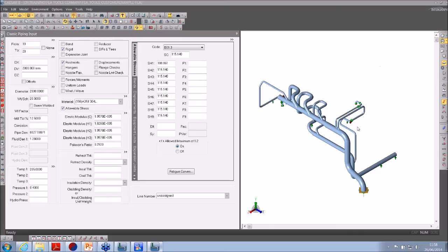The typical design process, of course, is changing restraints or modifying the piping system a little bit. And if you've got more than a dozen or so load cases, it's oftentimes difficult to tell if you've made an impact on particular load cases. And so the comparison tool scans all the load cases and all the nodes and shows us the largest differences. So it ended up being a very convenient tool for comparing 4, 5, 6, 10 different versions of CAESAR models to see which ones had the lower pump loads or the lower support loads, for example.